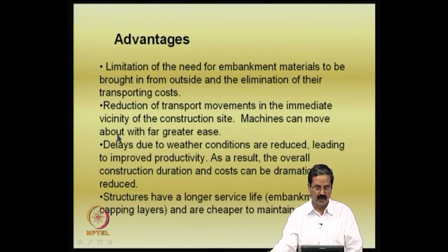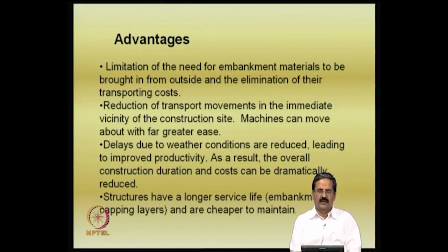Machines can move about with greater ease. What I just mentioned was that the soil is so poor nothing can move, but if you sprinkle some lime, definitely some reactions take place, and within a short time you can start using that. In fact, I mentioned a few minutes back that it takes 2 hours to have the initial reactions take place.